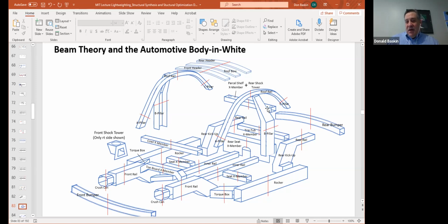One is that you want these materials as strong as possible to completely limit any intrusion. And also, because this is the place where the passengers live, you need as little room for structure as possible and as much room as possible for occupants, because that's a lot more comfortable. So you have limited packaging room, and you need as high strength as possible.